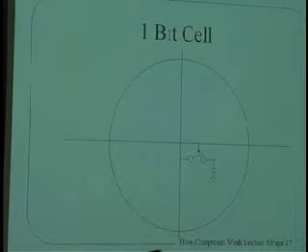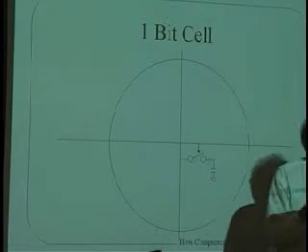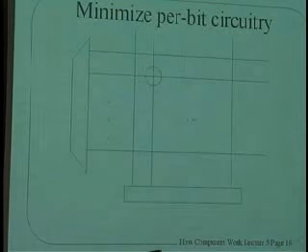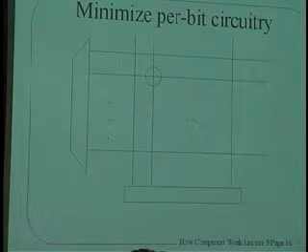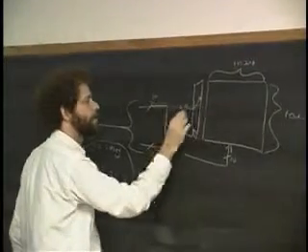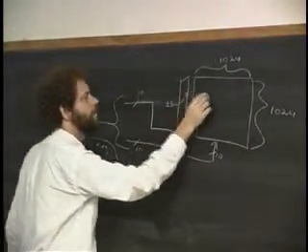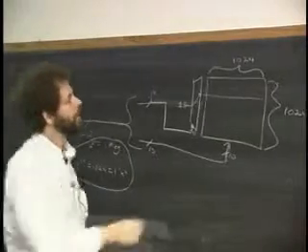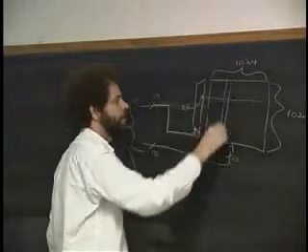Yeah? We're using selectors on each axis there? Let me make that a little more clear. I think on the previous one, I used a square at the bottom, which wasn't quite so nice. Here's what I'm going to do. I'm going to use a decoder over here. Okay, I'm not drawing this quite right here. Let me draw this right. 10 bits go in here, and I'm going to put a logic 1 in there, and that's going to choose one of the rows. Okay? And then all of the columns are going to come down like this.